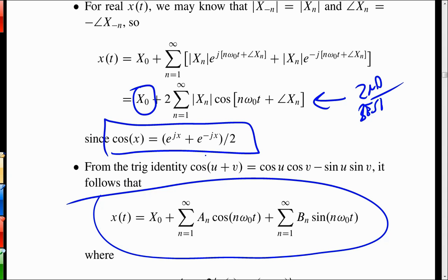And what does x0 actually do in the waveform? It just talks about whether you're raising or lowering it. Again, a coupling capacitor on a waveform will make that one go away. And in the lab, the spectrum analyzer has a coupling capacitor on the input, so you do not see a spike at DC. If you see a spike at DC on a spectrum analyzer, it's added artificially. Sometimes they will add some reference line or something, but it's not part of the waveform. It's AC coupled.